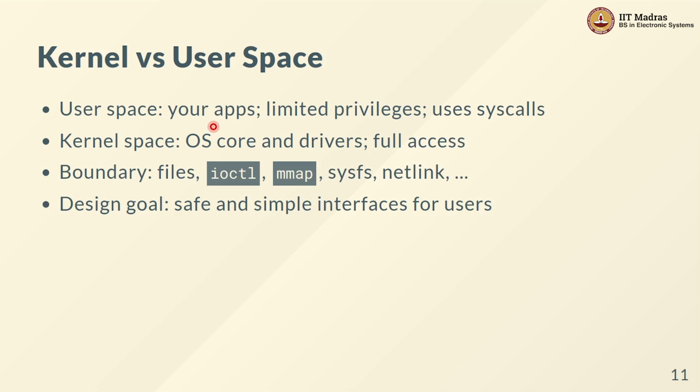And so how this happens is that even for something as simple as accessing a location in memory, or perhaps reading something from disk, you cannot directly go and activate the registers corresponding to that peripheral and try to pull data out of it. Let's say we are talking about a PWM timer module. I cannot allow some arbitrary user to just go in there and directly start poking at address 4000, whatever that number was, right?